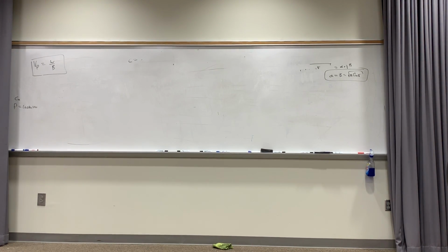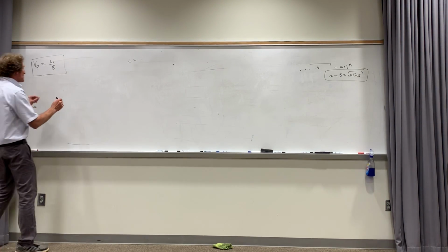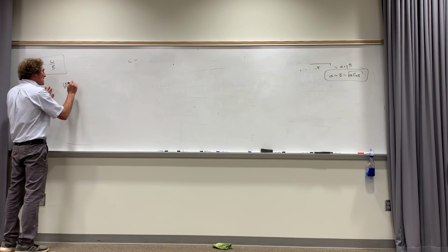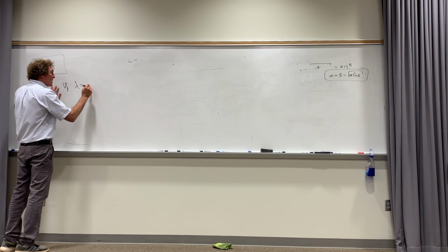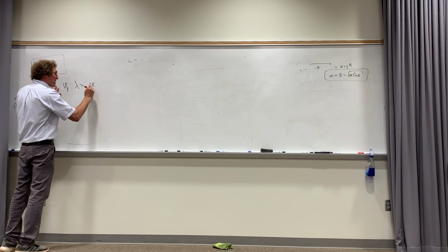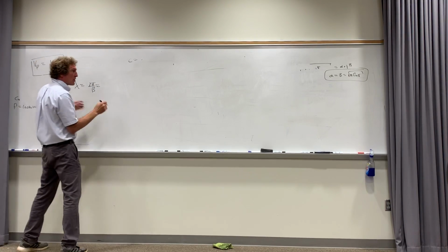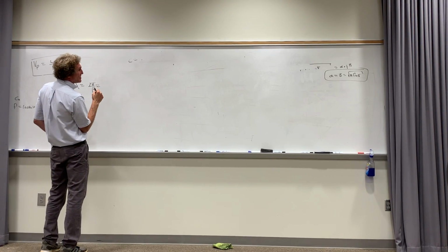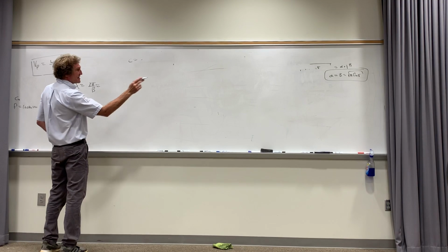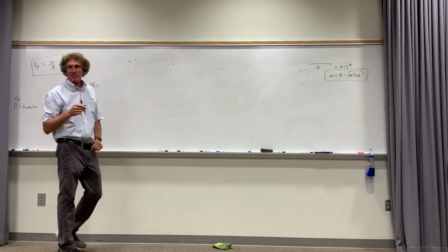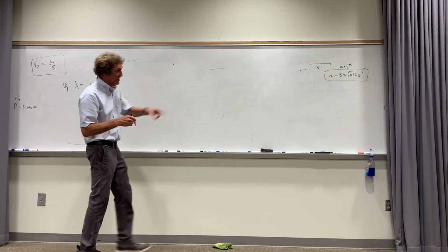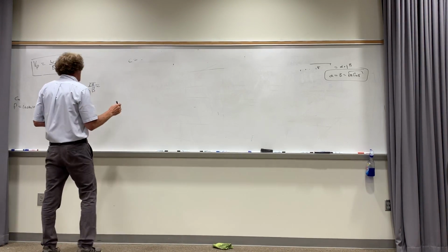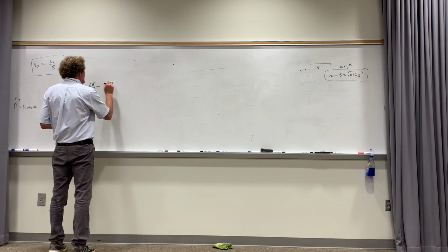Remember this. This will help you. So that means the wavelength would be equal to what? 2 pi over beta. And what is that going to be for ours? I forgot what beta is. Did we even calculate beta? We didn't calculate propagation constant, did we? Well, we can, since it's right there, we can calculate. But for ours, it's going to be 2 pi, right?